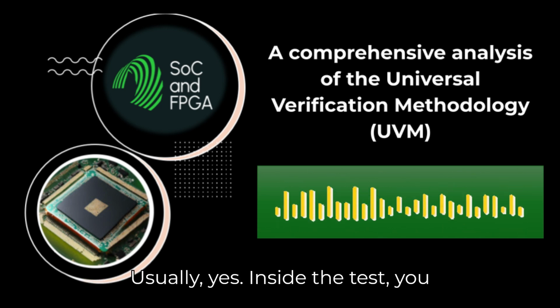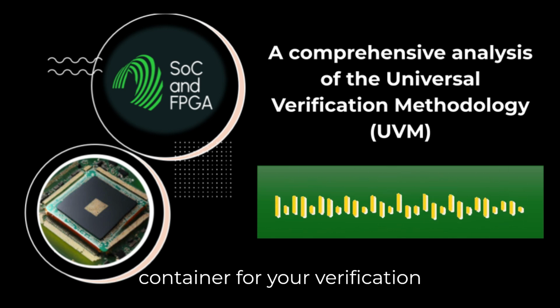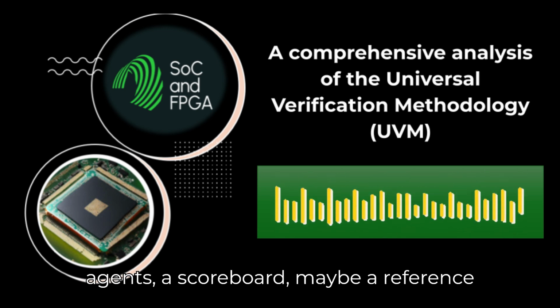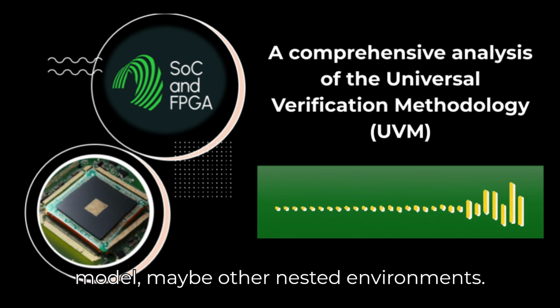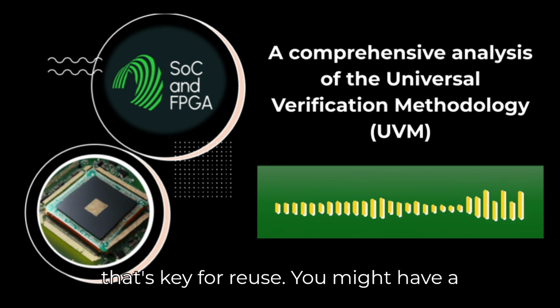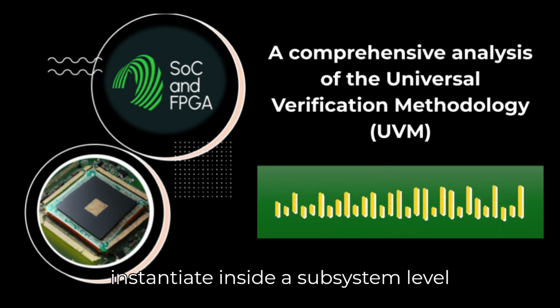Usually, yes. Inside the test, you typically have a UVM environment. This is the main container for your verification components. It might instantiate several agents, a scoreboard, maybe a reference model, maybe other nested environments. And environments can be nested. Oh yeah, that's key for reuse. You might have a block-level environment that you then instantiate inside a subsystem-level environment.